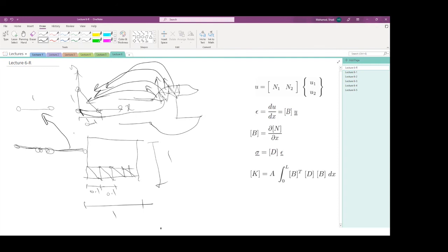you can simply multiply them by a scaling factor if you want. So if this is 1, and this is, I don't know, L over 5, and this one here is L over 2, and this one here is L over 20, and this is L over, I don't know, 3, for example. So you can just multiply them by the scaling factor, and you can map them into this new mesh. Right? The process itself is so easy for 2-noded elements. However, I'm going to derive it for the 2-noded element using the full-length procedure so that you can understand it. And then we are going to move to the 3-noded element, and then I'm going to explain it for 2-dimensional problems. All right?